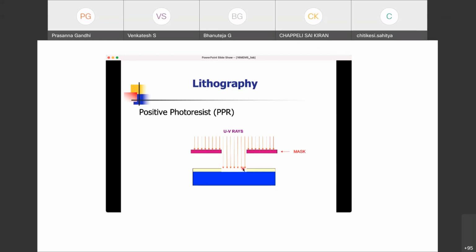So the wafer comes out of your lithography machine already exposed to UV light, and then you insert it into a developer bath, and the part where the UV light has fallen will get etched away.